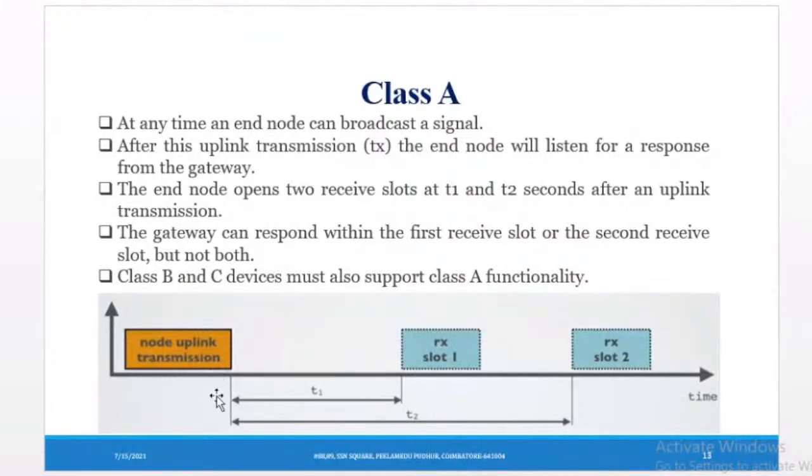It will take the data depending upon the uplink transmission time which I give. For example, here I have given 5 minutes. Till those 5 minutes, my RX1 window and RX2 window are closed and my node is in completely sleep mode. Whenever the timer triggers, that is, the 5 minutes elapse, only then will my node wake up. It will take the sensor data and push the data using the RX1 window slot. After this, what happened?